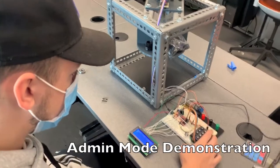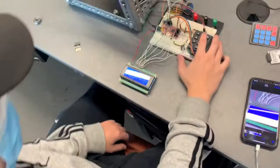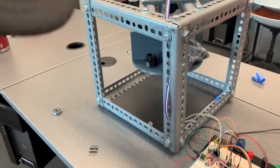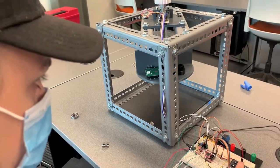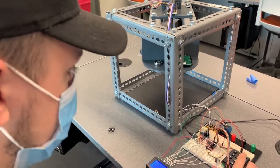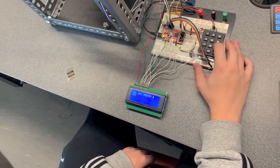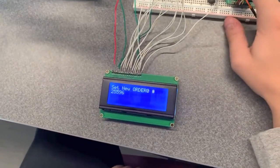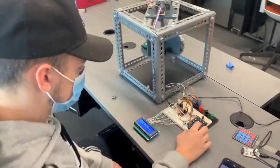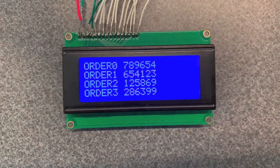Chris demonstrates entering the admin password to enter admin mode. The admin screen appears with options to calibrate the carousel's position and set new order numbers. He selects setting new order numbers as the program recognizes the empty cells of parts retrieved. This automation allows the staff at the HVAMC to place in parts and set new order numbers with ease and certainty. The cells, parts, and numbers correspond properly. He places the part in the space and enters a new 6-digit number to be saved. Calibration mode allows for fine-tuning of the initial position of the carousel in this mode as well.